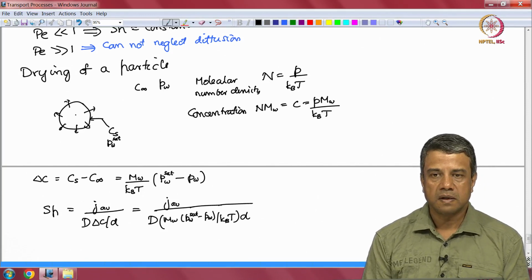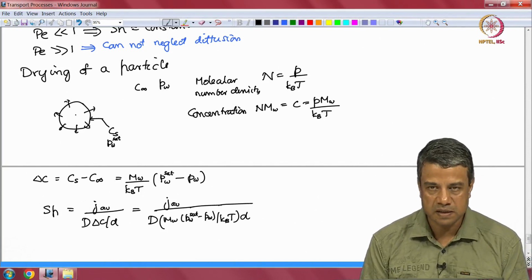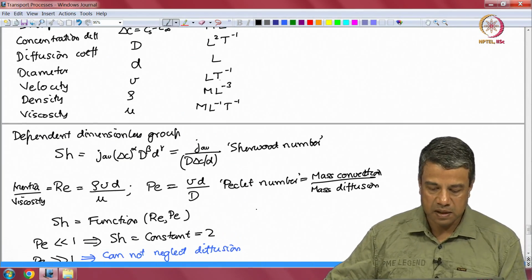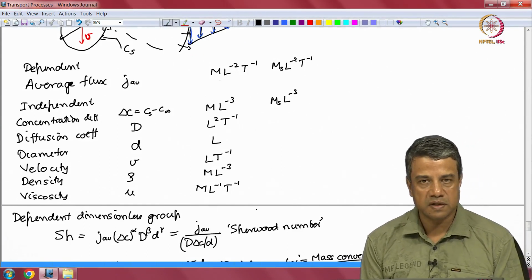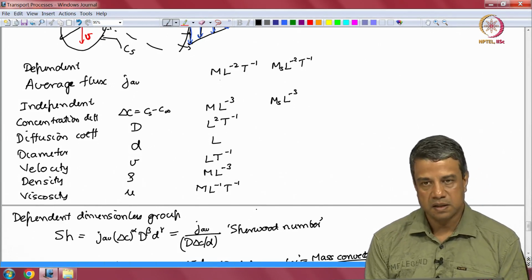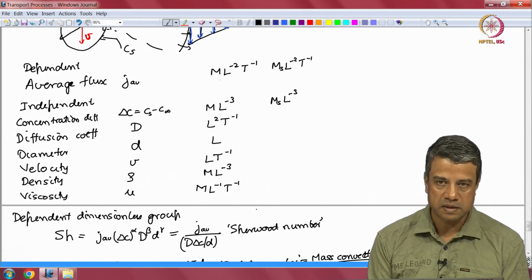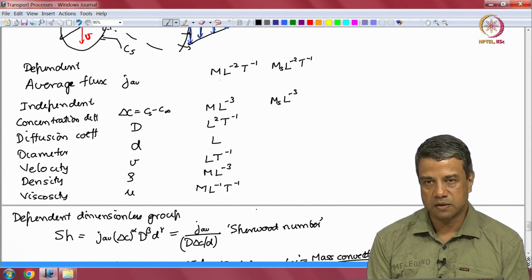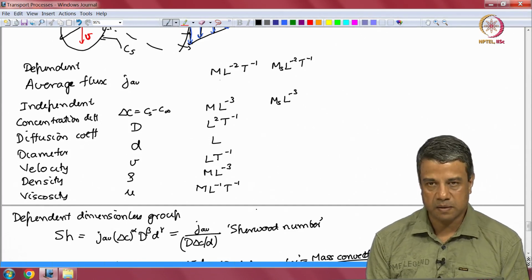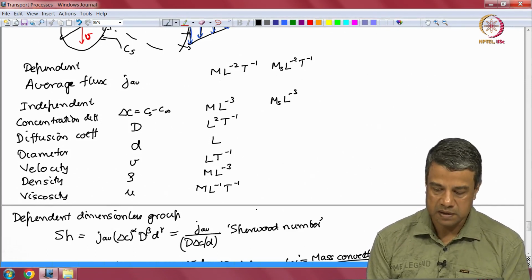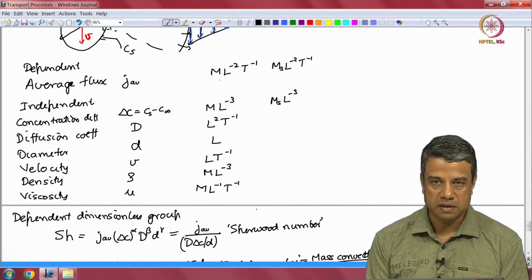So, I have determined from dimensional analysis a relation between dimensionless groups. Dimensional analysis and one additional input, and that is that there is no interconversion between the mass of solute and the fluid mass, that is, the change in concentration does not affect the fluid properties. This, of course, is an approximation. If the change in solute concentration affects the fluid properties, that has to be incorporated in this. If it does not, there are 4 dimensions: solute mass, total mass, length and time.